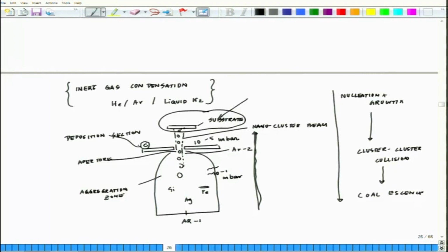Similarly, you have electron beam evaporation, EBE technique. Okay. EBE or electron beam evaporation is a vacuum based, again all these are vacuum based physical vapor deposition processes, which is used to fabricate the thin films of nanomaterials. An EBE system consists of vacuum unit, electron beam source and target material. Again you see, you have a vacuum unit out here, as I showed you, aggregation zone, which is a vacuum unit. Then you have electron source, and then you have a deposition ground.